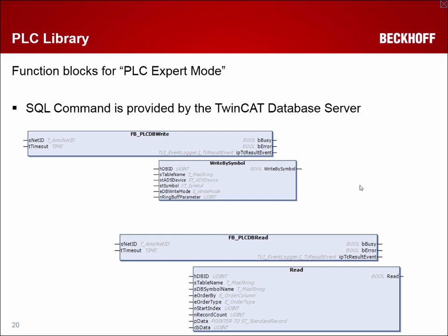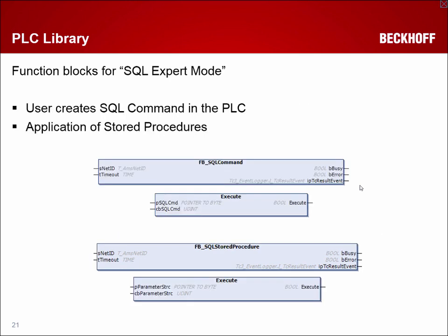And if you say, hey, I need much more performance and I'm a SQL expert, then you can choose the SQL expert mode, and there we have a lot of different function blocks for you to do exactly this by yourself. So this is the creating of the SQL command in the PLC, and for this you can use the FB SQL command, for example, or if you would like to start stored procedures from the PLC controller, then you can use the FB SQL stored procedure function block.